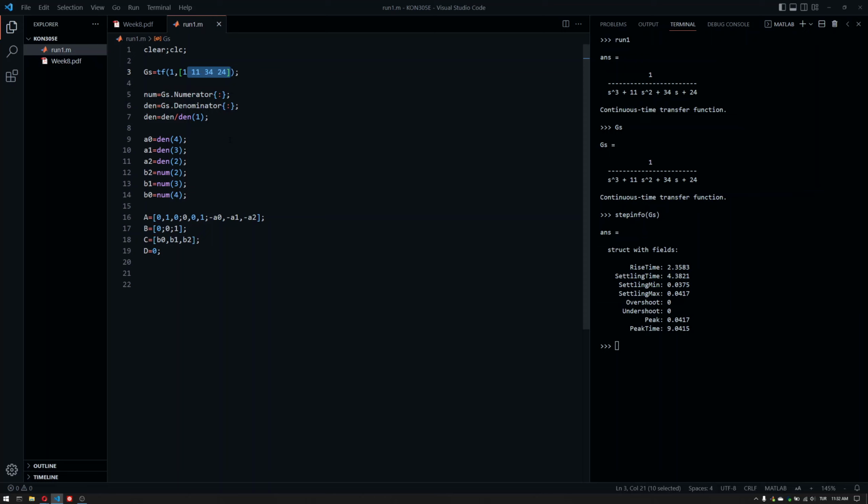Or if you don't even have that capability, what you need to do is use a while loop and then check if we are reaching the settling time whilst we are doing all this calculation down in a moment. So basically you then are not going to define a settling time. You will just pick, for example, a 1 millisecond sampling time and try to solve it on the fly.